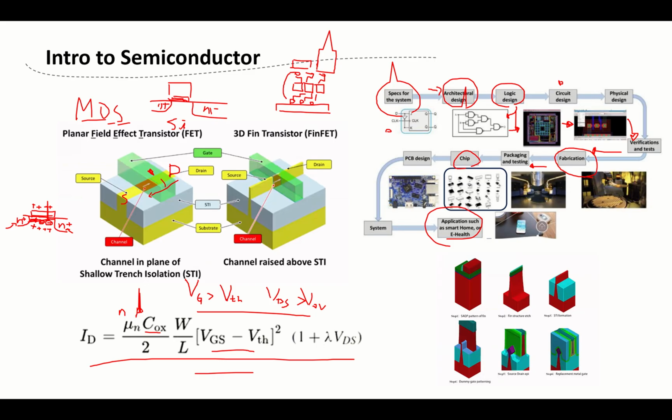And also we can play around with the VTH over here. We can change the oxide, or we can change the metal to tune it. Then we will have a width, which is this part of a MOS, and we have length, which is this part.